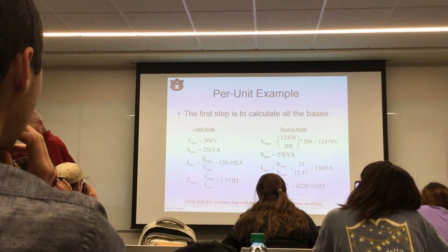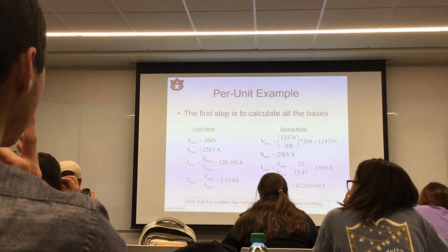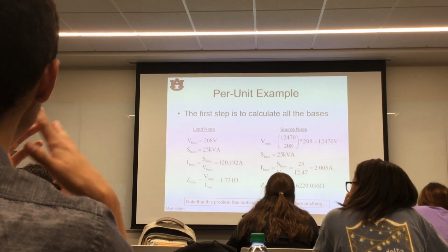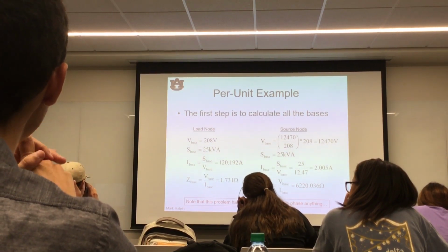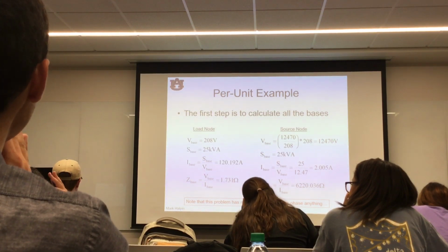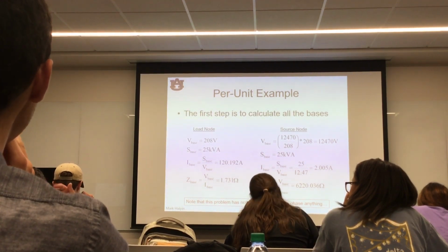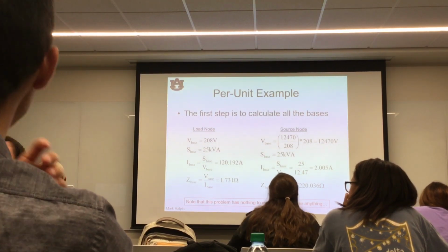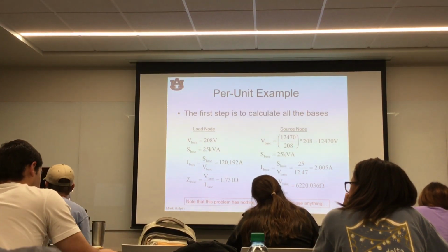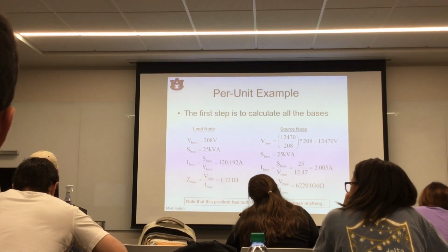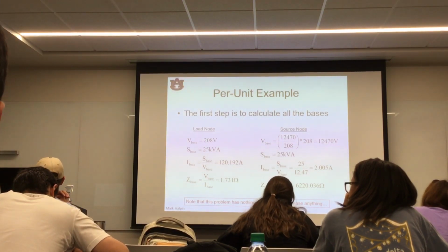Sorry. So you have to know whether it's connected in wye or delta before you pick your voltage base. And careful with that. Kinda yes and kinda no. Applications where you make three-phase field connections with individual transformers can be a little bit tricky.